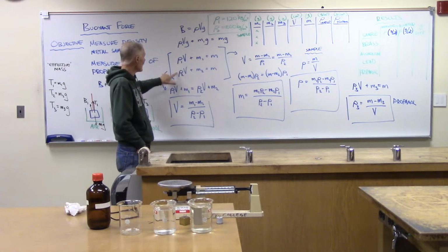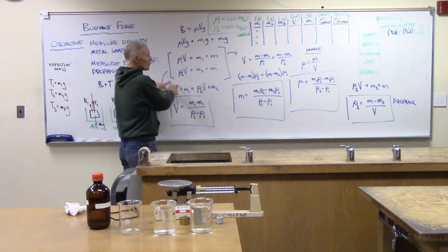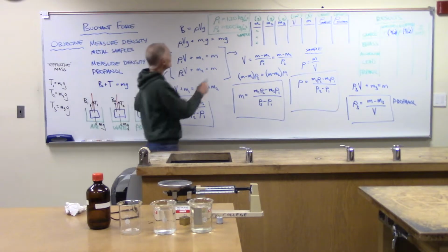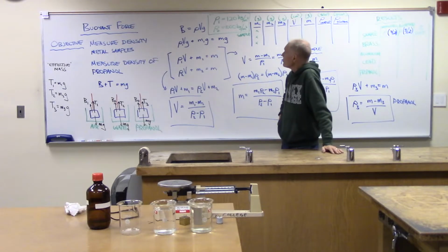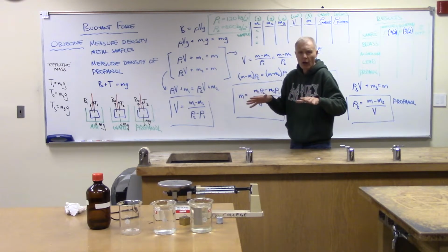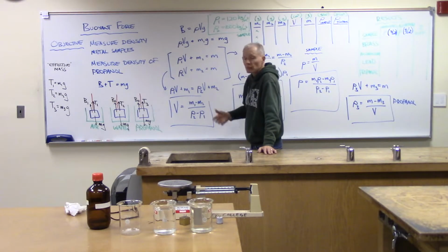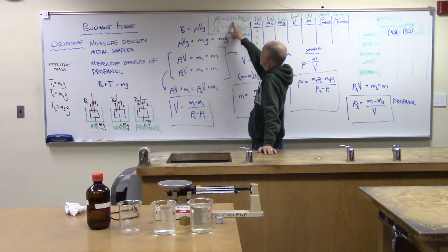Okay, and then I can write that down for fluid number 2, and I can write it down for fluid number 3. So I'm going to get three formulas. Now I'm going to start off with just these two. I'm going to start off with the air and the water, and that's because the air and water densities we're going to say are well known. We're going to assume that the air we're working with is at ocean level, which the altitude here is pretty close to, and roughly 20 degrees Celsius, then the density is going to be given by 1.20. So that's a pretty reliable number.